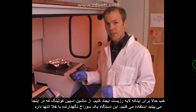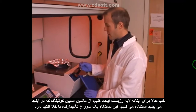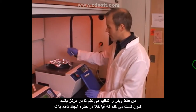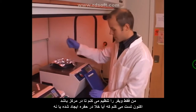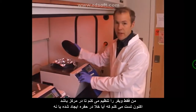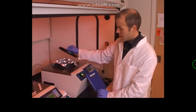So to apply the resist layer, I'm going to use this spin coating machine here that has a vacuum chuck on top. I just set the clean wafer in the center. And then I'll test to see that the vacuum is holding by starting the machine.